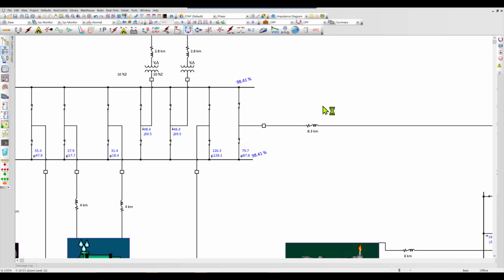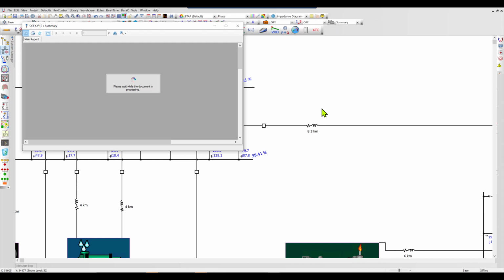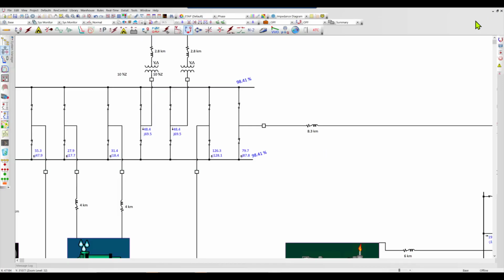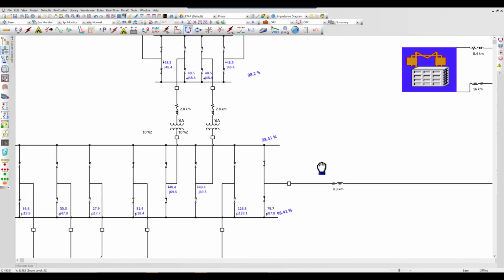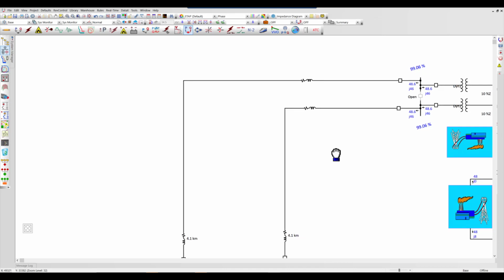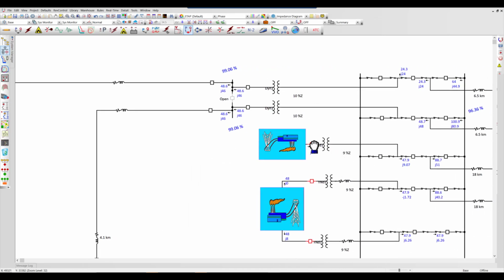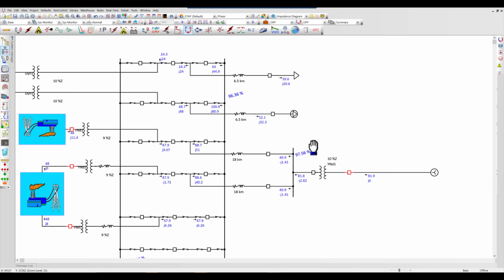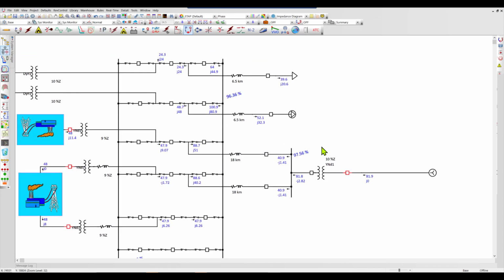Now, when we go back and look at our summary and see whether that has impacted in any negative manner, we can see that no, we still have about 2 megawatt of real power savings in the system, and we have managed to bring the voltages within a flatter profile of 100% throughout the system, while bringing in generation economy and of course keeping our voltage security closer to 100%.